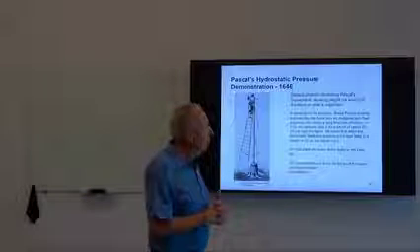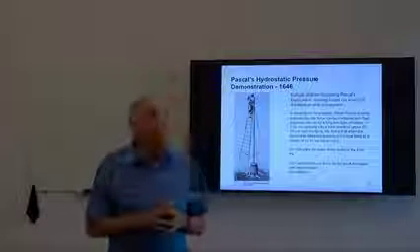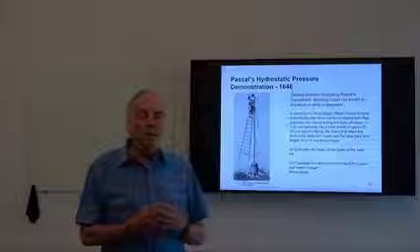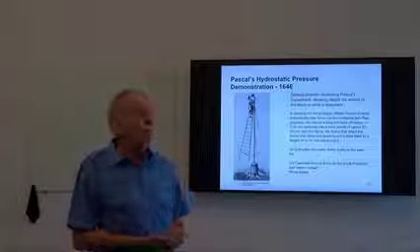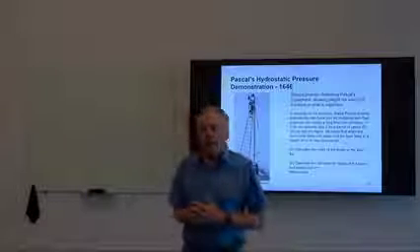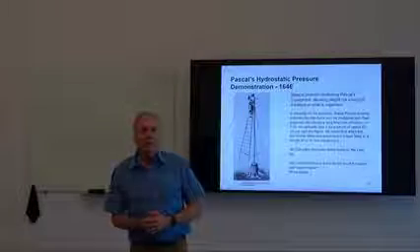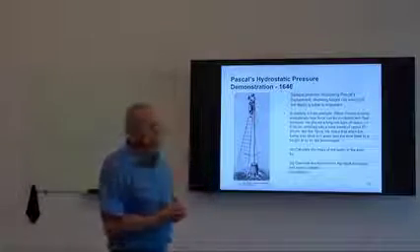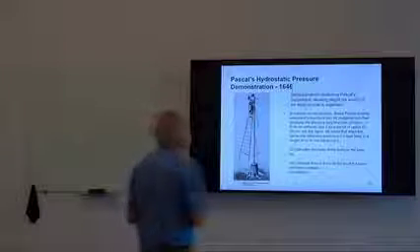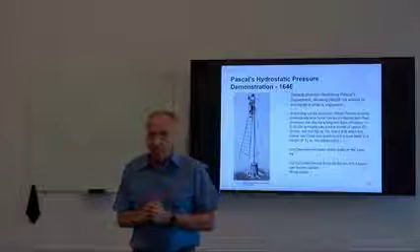Let me talk a little bit about why it's the height, because every once in a while I find that we have the sense that it is either the volume of liquid or the weight of the liquid column. This is a term I used to hear a lot many years ago, and still occasionally comes up as I teach my classes. But it is truly about the height of the liquid column. And this harkens back to the famous Pascal demonstration from 1646.